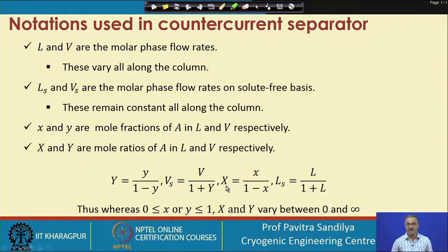So, similarly we have the mole ratio in the L phase related with the mole fraction in the L phase, and the solute free flow of the L phase related to the total flow of the L phase, and this will be x, this is the mole ratio. So, this is how we are able to correlate the mole ratio with the mole fraction and the solute free flow rate with the total flow rate.